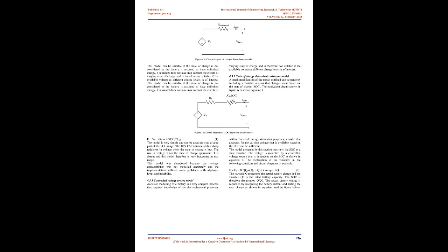For a reliable generation system that can function independent of the utility grid, however, batteries may be a viable component of the total system. Backup generators may be included in a system to provide power when the PV system is not operating, and are generally included when systems are not grid connected. Neither batteries nor generators are eligible for rebate money.